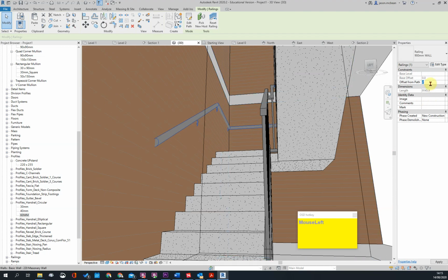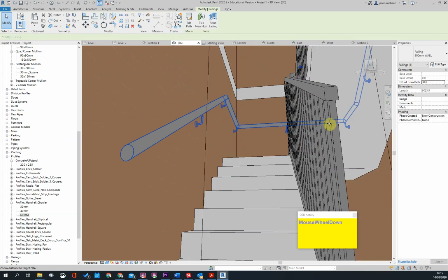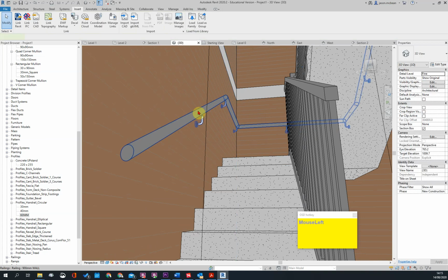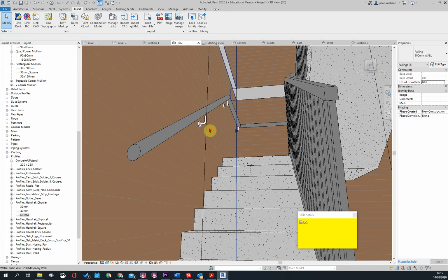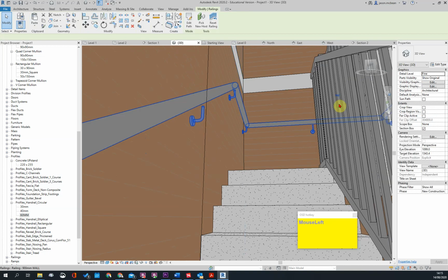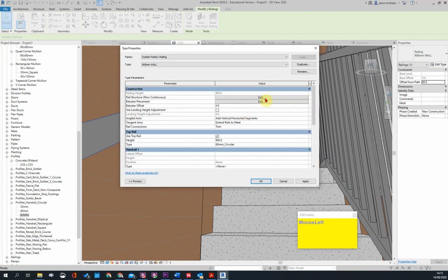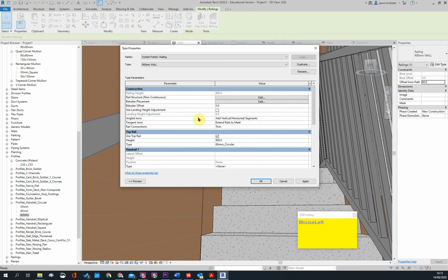So here, usually it's about 30mm we offset it from the wall. Here I just have to adjust how this family works, so maybe 45. Then let's make it 60. That's it. Then I've just got to adjust where these work from. So here I'm going to say edit type. These adjust from top elements, so base offset minus 50, press apply.